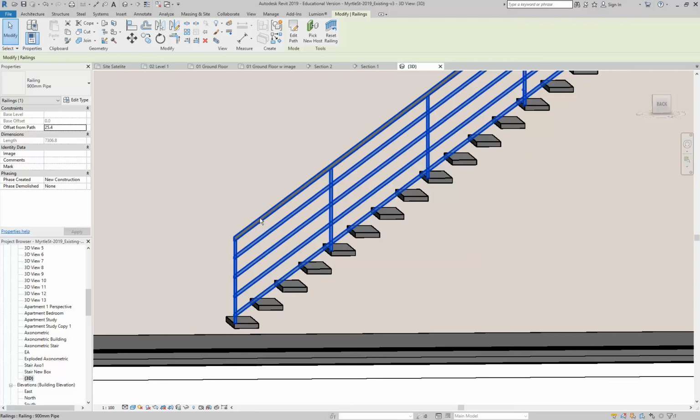They might not be too picky with your designs for this project. You might be able to get away with more of a conceptual stair and not show the handrail with all the detail that you should have. But in real life, it's a huge thing now, not just having the handrail alongside your stair, but you've also got to have a projection for public stairs, not for private, but public stairs. It's got to project out at the end. You'll see it now in a lot of buildings where they stick it out for, I think it's 300mm or so, straight, horizontally, at the end of the stair.